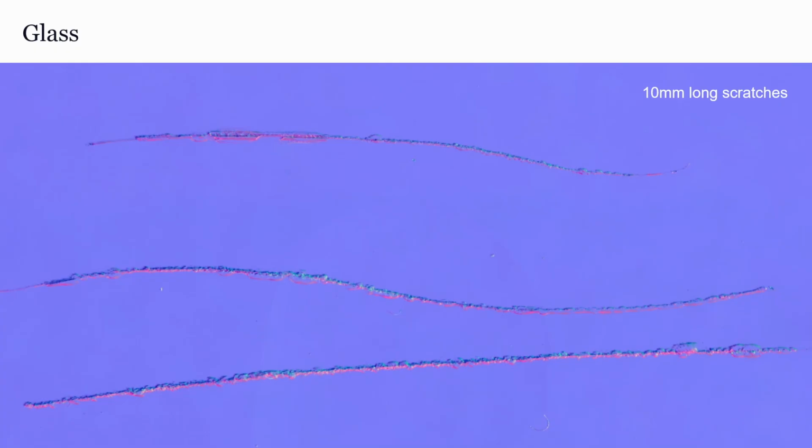This is quite amazing. These are 10 millimeter, so 1 centimeter long scratches on glass, and you can actually see they almost form this organic shape like a rope as those chips come away from the lines made by the carbide scribe. But scratches and fractures, they will show up on glass, and they clearly manifest based on their type and structure of the way those are formed in the crystalline surface of the glass. So that ability to pick up these very, very difficult to see defects is really powerful.